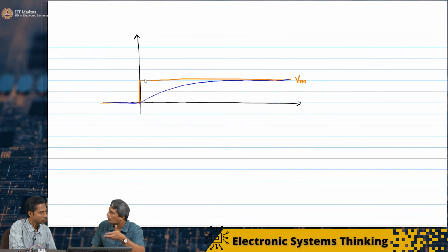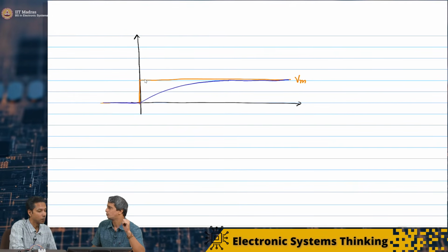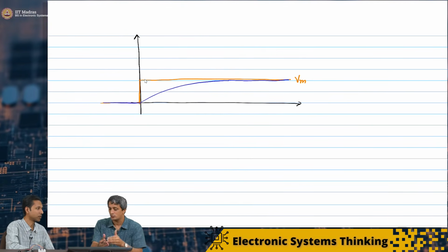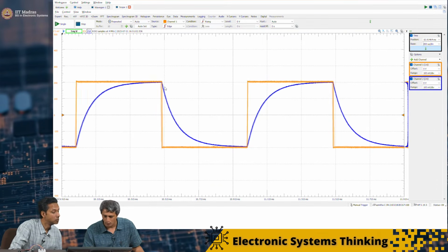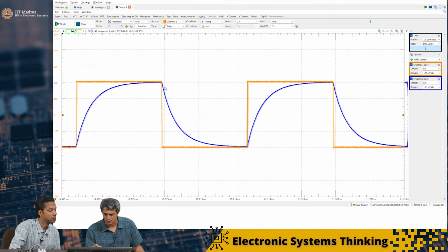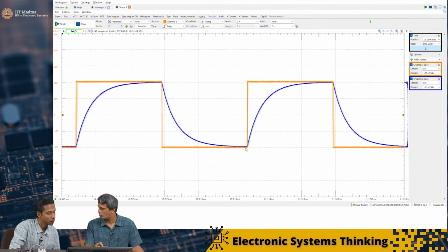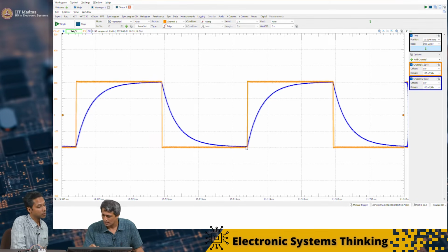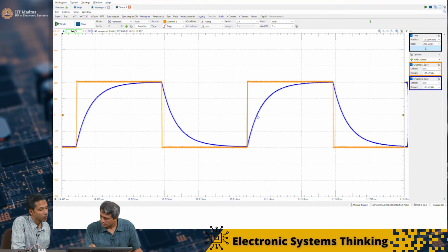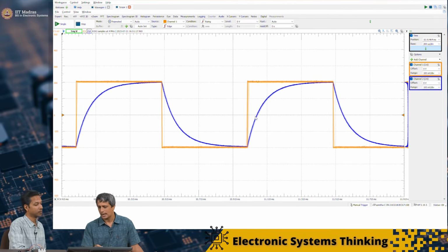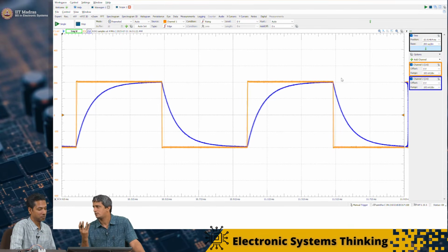Now, at what point will the capacitor reach Vm by 2? It seems to happen if you look at this, right? Let's look at this. Vm by 2 is what? This is some minus 200. By the way, in this case, it just so happened that we have applied a negative voltage also. Doesn't matter. So then we can look at when it reaches 0. Actually, it reaches 0 very quickly, right? And then it takes a long time to go. That's the nature of this exponential charge up.